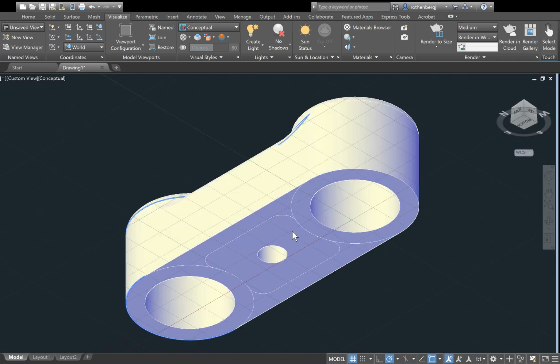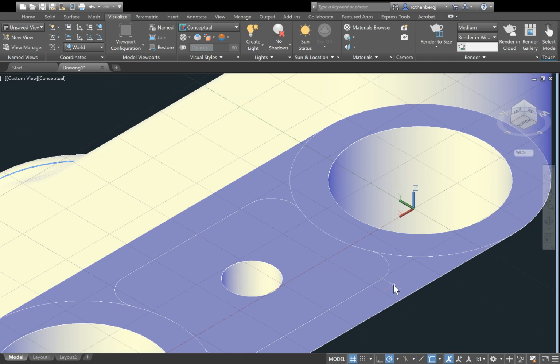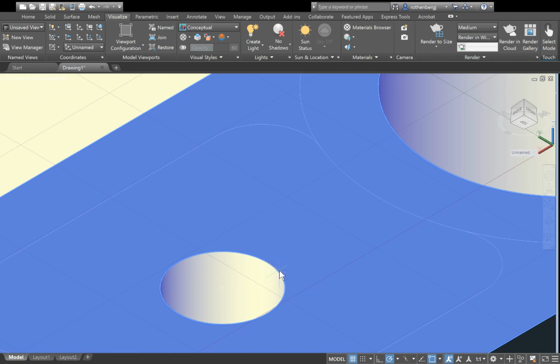So now all that's left to do is take out a corner to make it broken out. So the main difference between this and a half section is that this is more or less arbitrary, but just to make it look nice, I'm actually going to make it half the distance between this point, and this point. I think that gives us a nice cross section. So if you're going to do something along those lines, make sure that you select the quadrants, not just a near point, or else it won't be quite right.